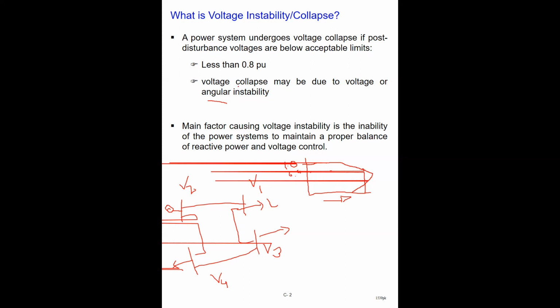In fact, here voltage collapse takes place, and that is the voltage instability. At a later stage, it is the rotor angle instability into which it is transformed. So in system stability, it is the voltage instability at first, because at this bus the voltage collapse takes place, and at a later stage the system instability will get transformed into rotor angle instability here.